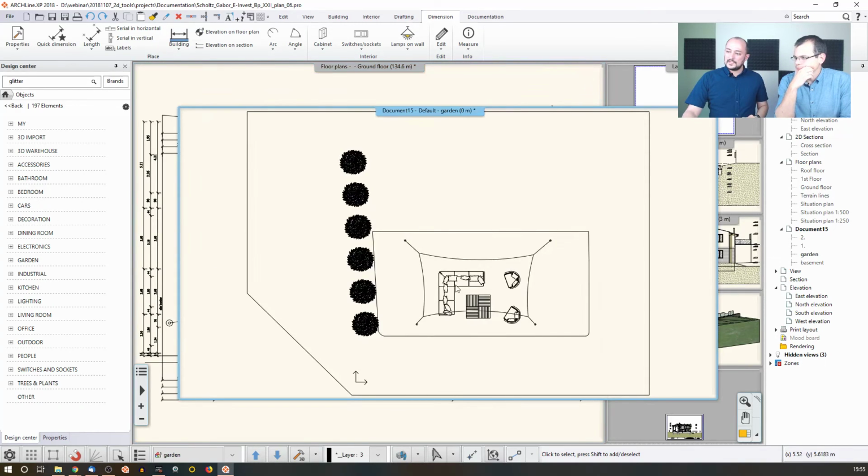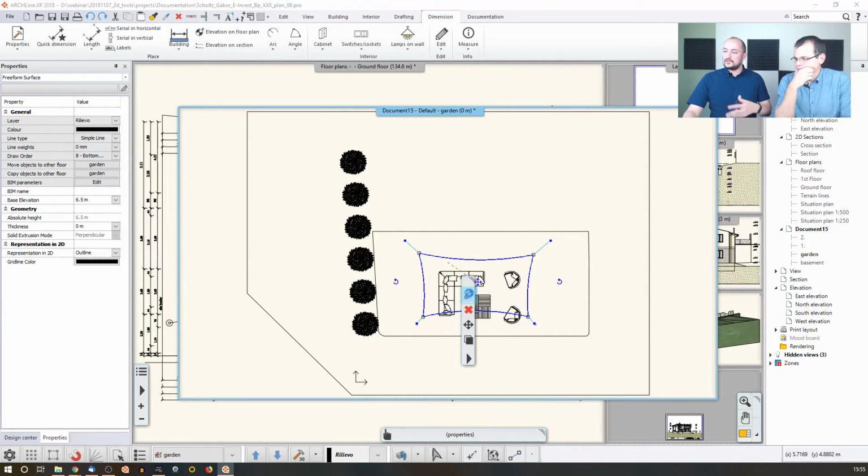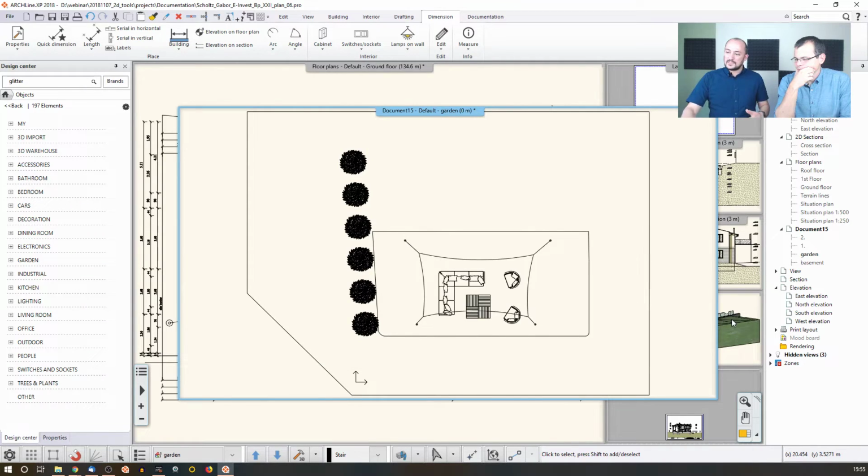If you work on this specific content, if you say, okay, let's just edit it and do anything I want and click OK, sometimes these things just merge together because you actually work continuously on two different things, and the software has to keep these two things updated. But to keep it clear, you just click on the drawing. Do not select anything, because in that case the software will only generate the selected thing. So I'm not selecting anything. I just click on 3D and it's generating the 3D of this. Or if I click in the other one and I click on 3D, it will generate the 3D of that project. And you can see in the project navigator that I have a floor plan with the building, and there's a document with the other part.